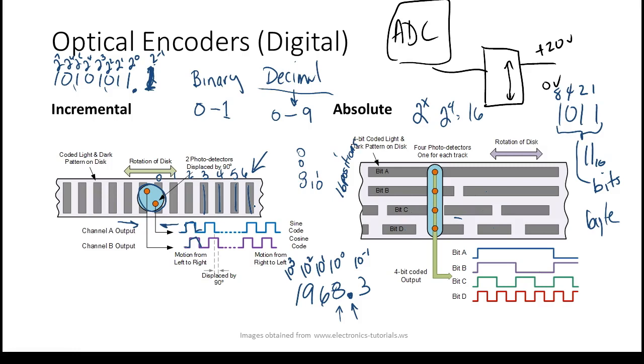But what we have to include with this is digital circuits that we call counters. If you have PLCs, you know that one of the things y'all learn how to set up is a counter. Now all I've got to do is count the stripes. What determines the resolution now is how many counts those counters can go up to.